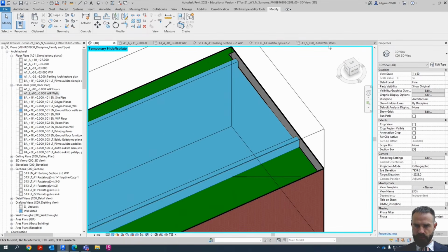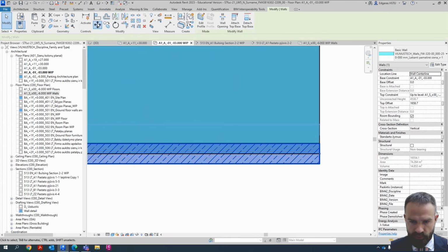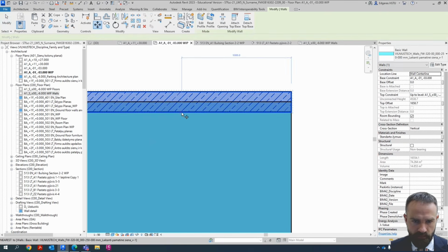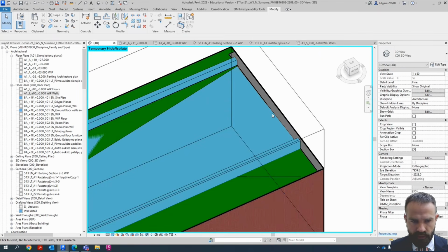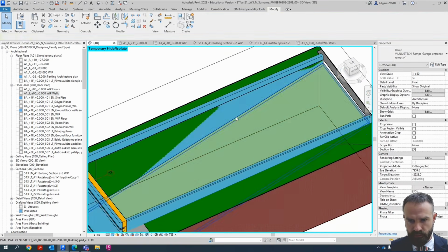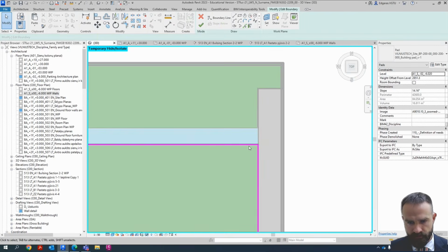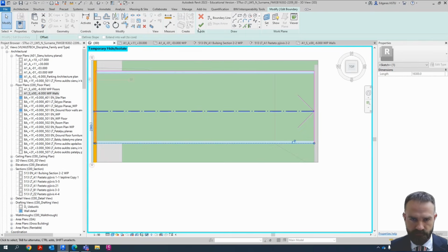Also, I should update the ramp construction. So for my building pad, maybe building pad, so it shows, so my wall goes, move the wall to the side of the ramp, move this wall also here, and the building pad also should be updated, because now I see my ground is inside my walls. So I hide my ramp and update the building pad. So the building pad should be grabbing also the walls.